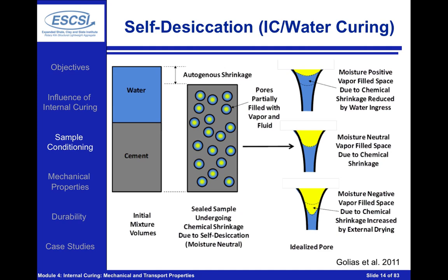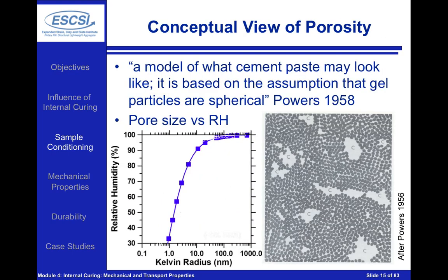So it's important to have this picture and how this represents different cases that you may come in contact with in real field applications. The whole idea is, by providing internal curing, we're providing additional moisture, leaving the lightweight aggregates filling in the pores, which would be very similar to water curing a concrete system.